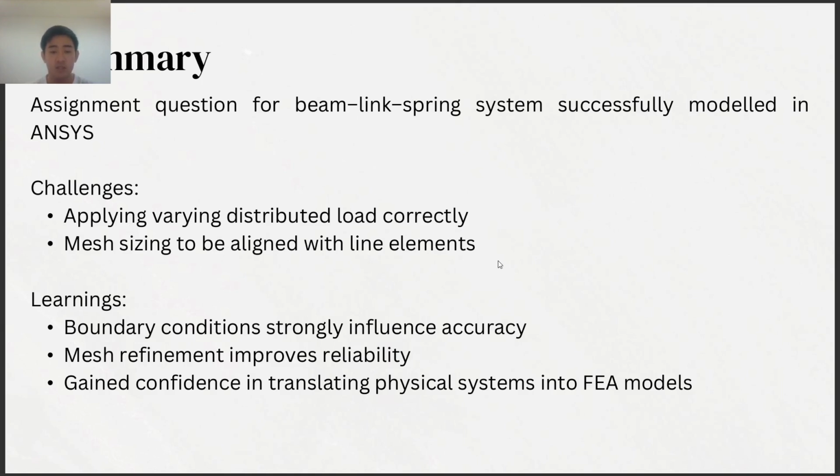What I've learned from this assignment is that the boundary conditions that are initially set will strongly influence final data accuracy. The same goes for mesh, so mesh refinement will further improve reliability of the system. Lastly, I've gained confidence in translating physical systems into finite element analysis models.